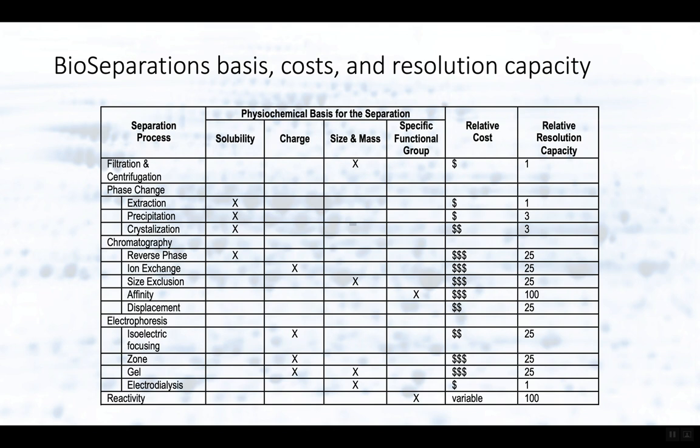You can think of this, the easiest way to think of this is biodiesel production. In biodiesel production, we extract the lipids from whatever the biomass is, whether it's algae or bacterial cells or plant tissues. We can extract the lipids from that. We then have to saponify those lipids to remove the phosphoglyceride and the glyceride head groups, and we're left with fatty acids. Now, those fatty acids, it's very difficult to separate those because they have low volatility because of the acid group that's present, so we can't easily distill them.